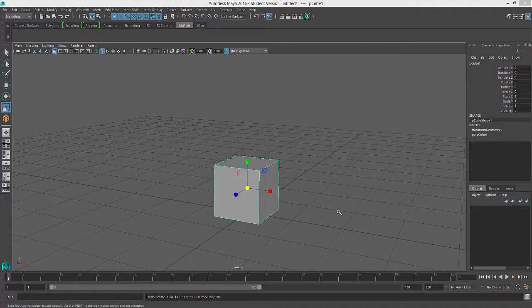So we've utilized a couple of Maya menu functions. We've utilized Freeze Transformation to reset our position, rotate, and scale in the channel box to 0, 0, 1 values, making the default value the new position that we've placed our object, and we've utilized the Center Pivot feature. If we want to utilize those over and over again, which you probably will, you might want to create shortcuts for them. All you have to do is jump into your custom menu tab within your shelf bar up at the top, and this is where we can create our custom shortcuts.